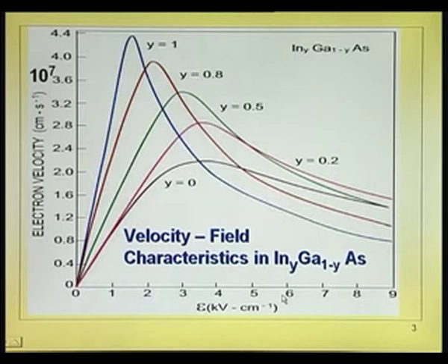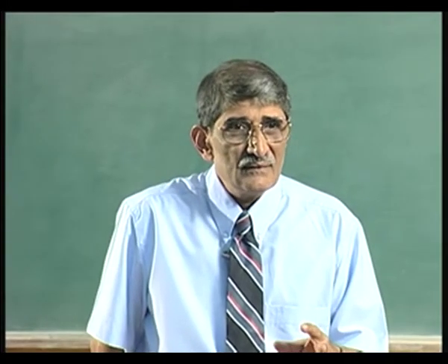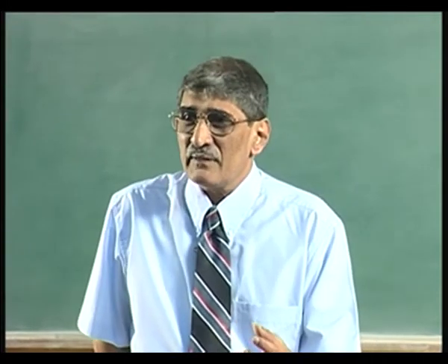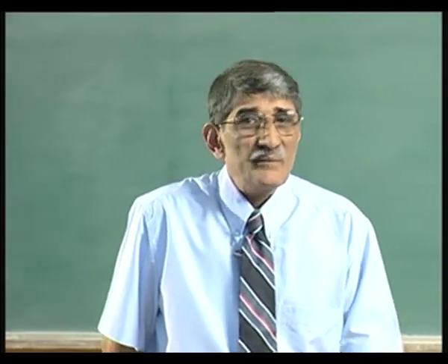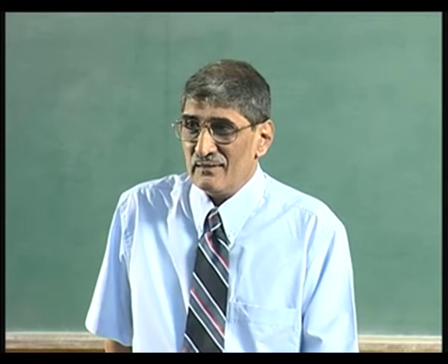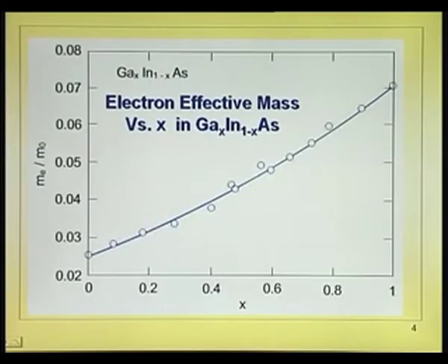Okay. So, what you are now looking for is the gallium indium arsenide based or indium phosphide based HEMT with indium phosphide semi insulating material. On the top of that grow gallium indium arsenide. On the top of that you must put a material which is wide band gap, okay, and that material must also match with gallium indium arsenide. In fact, it so turns out, we will see what those materials are, aluminum indium arsenide.